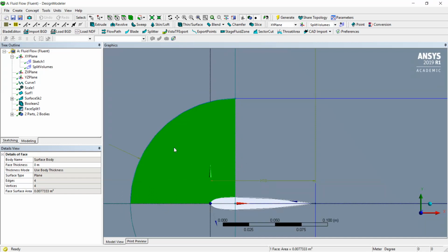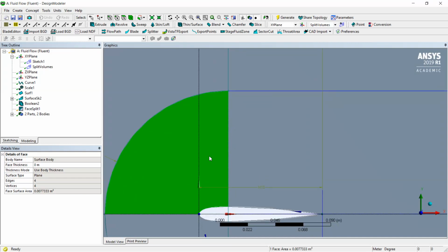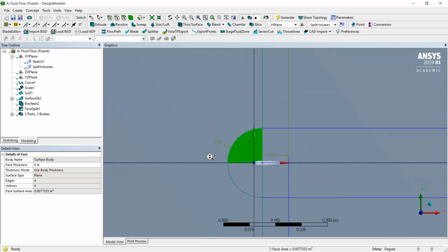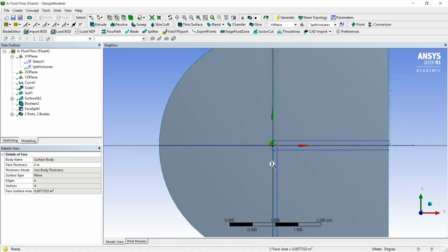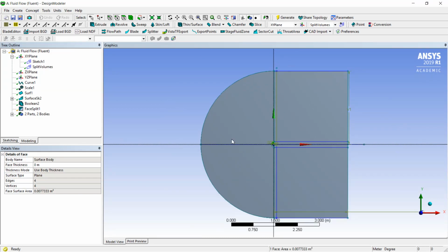They're opposite. Having the opposite edges is very important inside the meshing, so we can use special meshing tools, and we can solve many problems of meshing just if and when we split our complex volume into simpler 4-edge volumes. So every one of these volumes which I created has 4 edges.